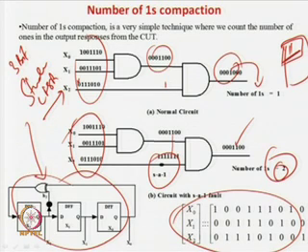The emphasis here is that we have done a compression from 7 bits to 1 bit, by counting the number of ones, and there was no aliasing for this fault. No aliasing for this fault means that even with this compression, if the fault is there, it can be detected, and if the fault is not there, that also can be detected.